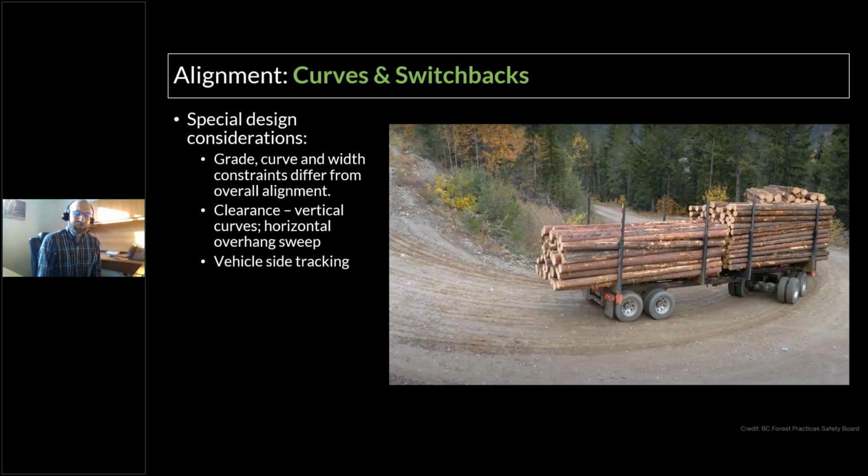Now, aside from these general curve considerations, switchbacks usually have design standards that differ from the rest of your road. It's common to want to reduce your grades through switchbacks. You're probably going to have a tighter minimum radius for your switchbacks than elsewhere on your alignment. And one thing that's important is you should give extra care to make sure that you have topographic relief to lose whatever cut or fill depth they've generated as you turn directly into or out of the hill.